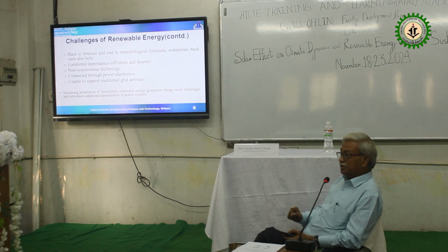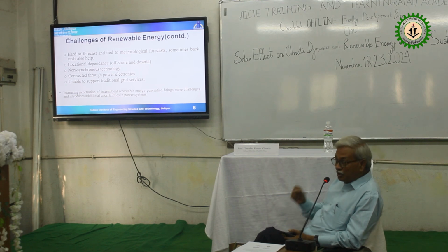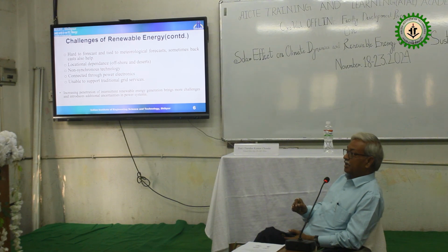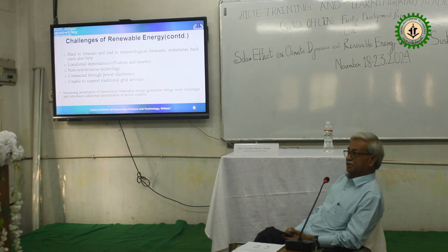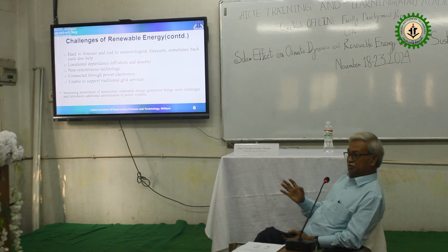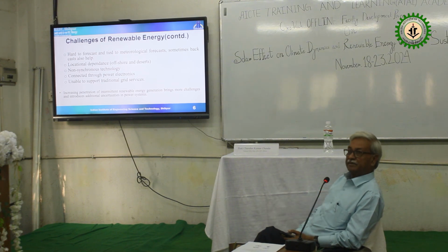So, intentionally or unintentionally, the moment we put in a converter, push-pull, buck, whatever converter is required for controlling the load, we are using power electronic devices and we are introducing harmonics. And harmonics completely jeopardize the total harmonic distortion of the system. Knowingly or unknowingly, we are inviting harmonics. But there is a solution. There is a prescription for that. The prescription is we can use an active filter, passive filter or hybrid filter to mitigate the harmonics.